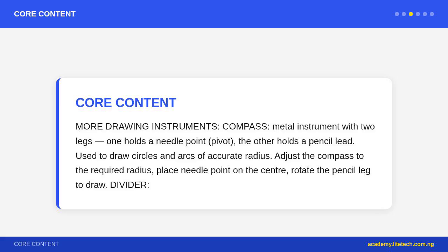Pencils and pencil grades. Drawing pencils are graded by hardness or softness of the lead, graphite. H grades: H, 2H, 3H, 4H, 5H, 6H are hard leads that produce fine, light lines. Higher H number equals harder and lighter. Used for construction lines and guidelines that will later be erased. B grades: B, 2B, 3B, 4B, 5B, 6B are soft leads that produce dark, bold lines. Higher B number equals softer and darker. Used for outlines and visible lines.